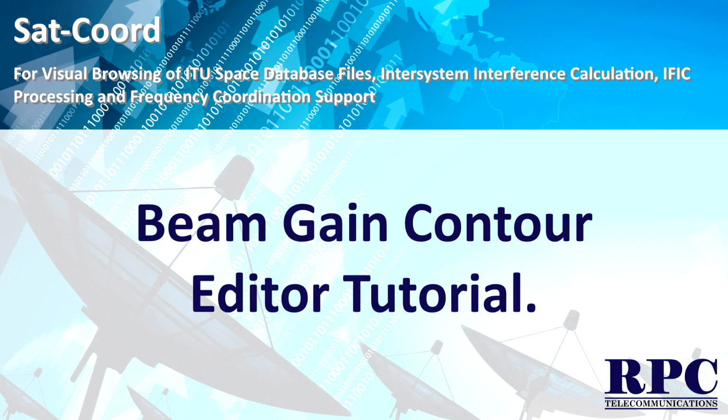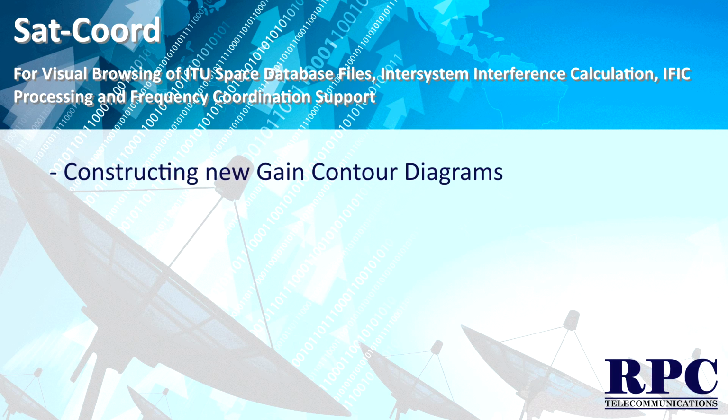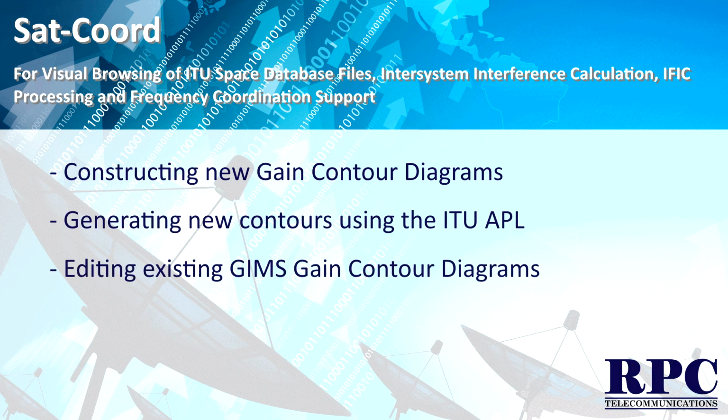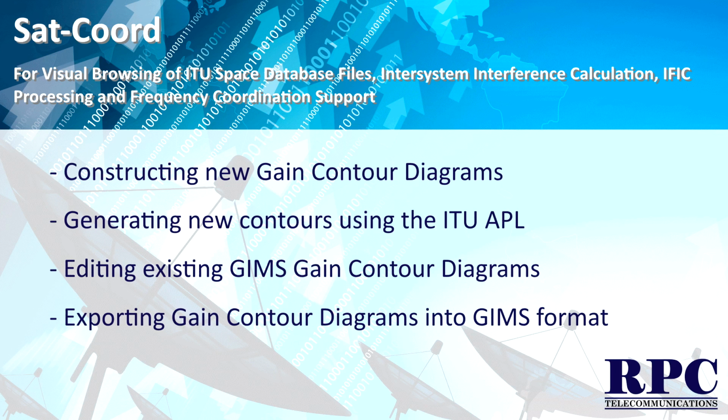Welcome to the Sat-Coord Beam Gain Contour Editing tutorial. In this tutorial I will show you how you can use Sat-Coord to create new custom gain contour diagrams from scratch, how you can use Sat-Coord to generate new contours using the ITU antenna pattern library, how you can edit existing GIMS gain contour diagrams, and how you can then export these diagrams into GIMS format files or databases.